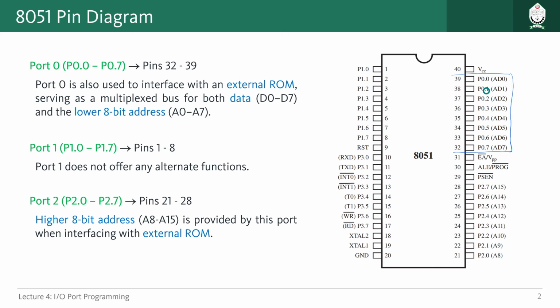So in those cases, the address bus and data bus has to be built through some mechanism, right? That mechanism is basically done using this kind of ports. So we know that for address we need 16 different pins or 16 bits, because our addresses are of 16 bits, and for data is 8 bit.